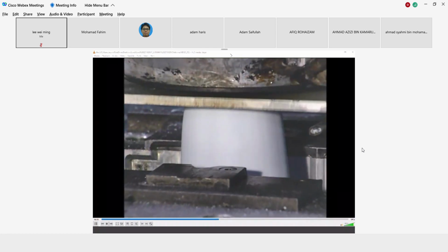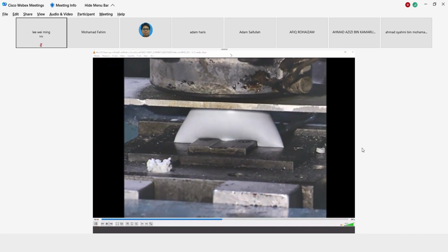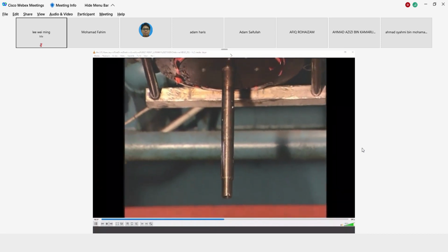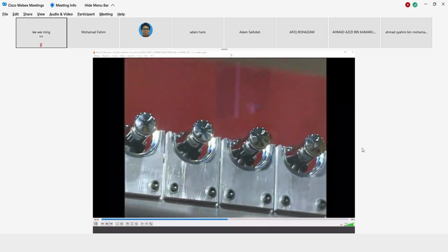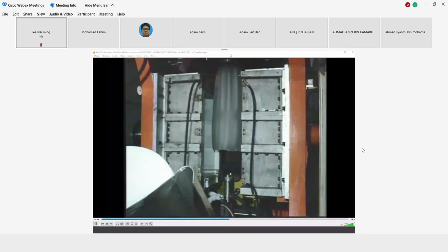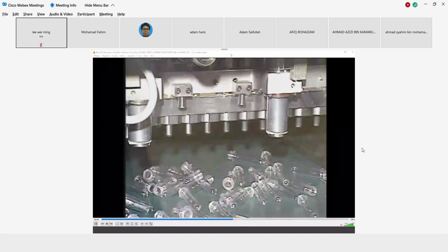For the most part, blow molding processes all use the same blowing technique, whether it be through a blow pin, a needle, a stuffer, or core rod. It is in the production of the parison, or the preform, where these processes differ.